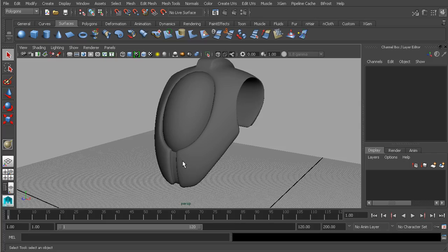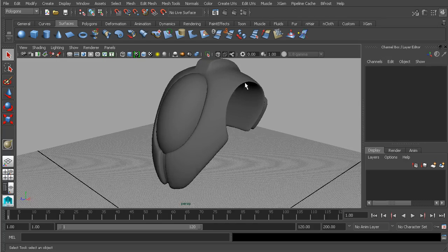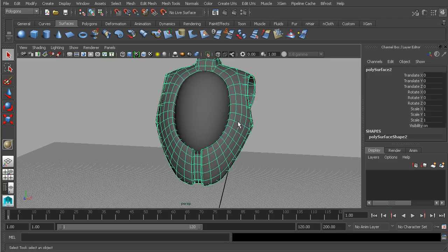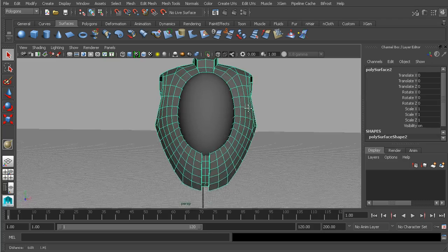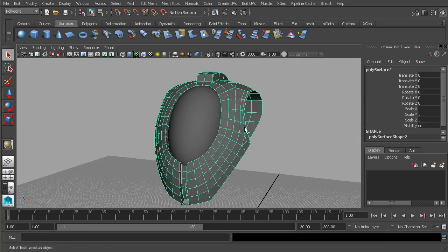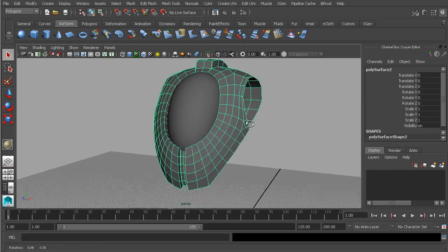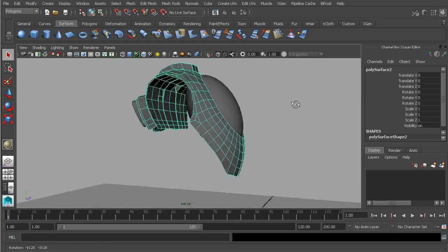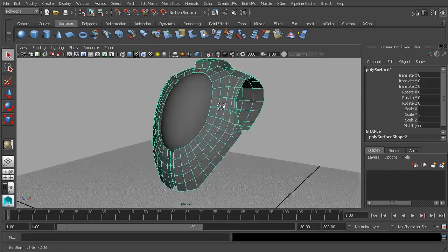Right now, as we talked about, this edge is really soft. There's also a really sharp edge here. We might want more of a flat plane coming down to give us the idea of a little bit of thickness. So we want to make a few modifications to this mesh. The nice thing about building this symmetrically is if we have to make some modifications, we can do that across symmetry, or we can delete the mesh and then mirror it back across.